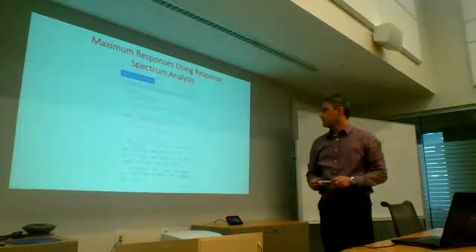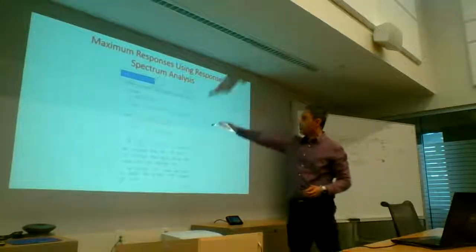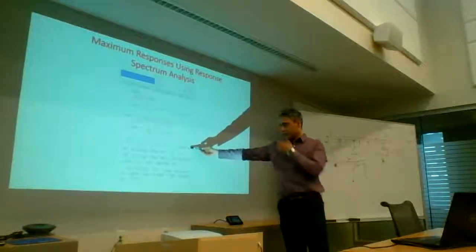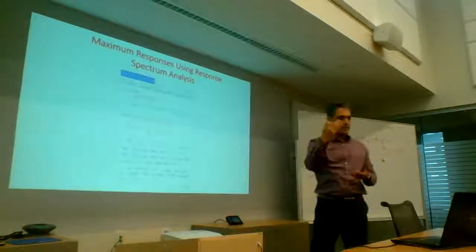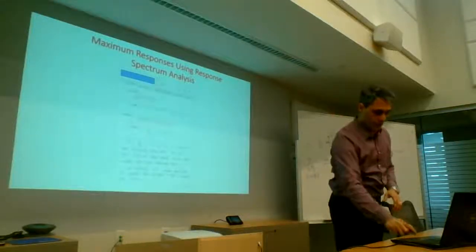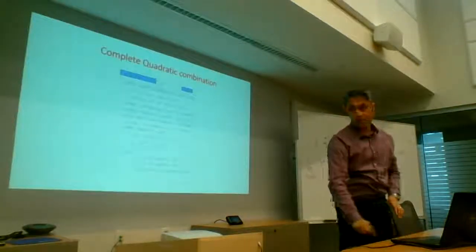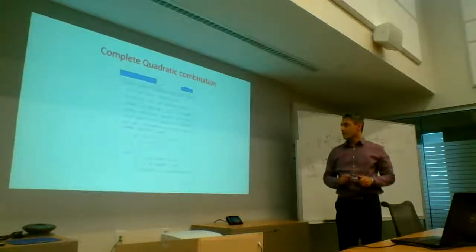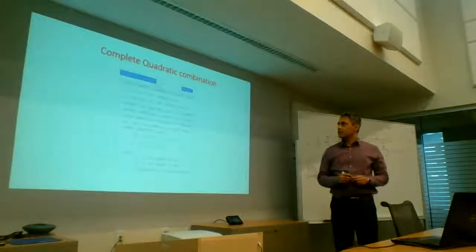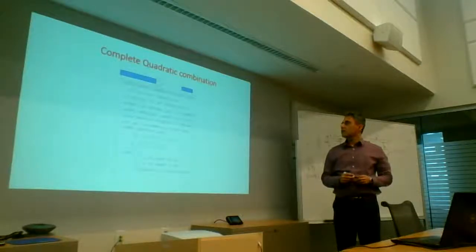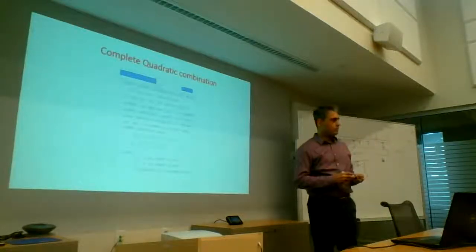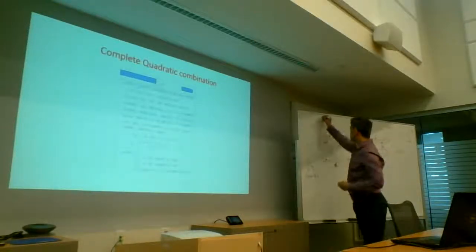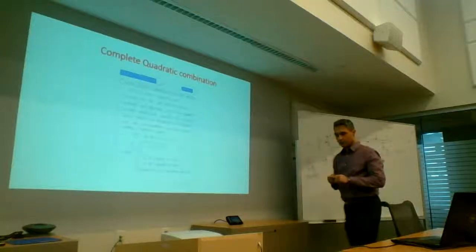Okay, so for each mode, you can have your base shear for your effective modal mass, like I was describing. It just turns into many systems of single degree of freedom. Now, in terms of the combination rules for modal combination, you can use SRSS, which is the square root of sum of squares.